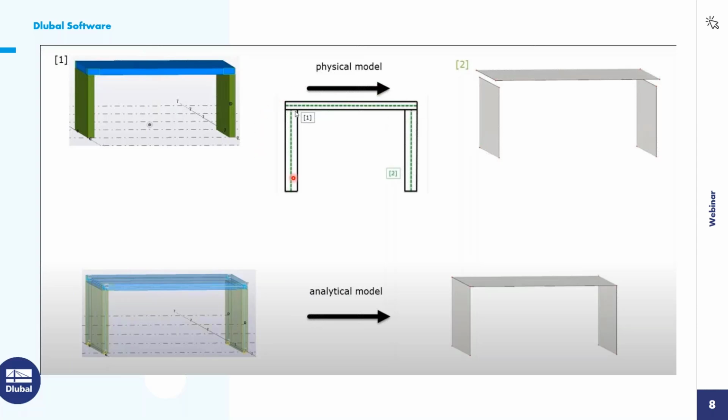If you export this physical model, you can see that the axial positions here are not lined up or connected at all. The wall here is basically just framing into the bottom of the slab, and so there's going to be a space there. So if you export this physical model, this is what you're going to see in RFEM, which isn't good.